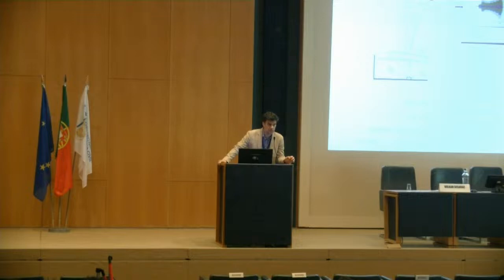So then, is there an application limit of your dynamic impedance function considering inelastic behavior of soil? No, we cannot do this. We have to assume elastic behavior of the soil. Okay, thank you. Otherwise, impedance functions for nonlinear soil behavior or equivalent linear soil behavior are very sparse. Of course, they are different.